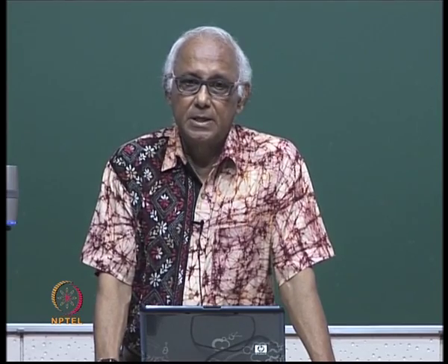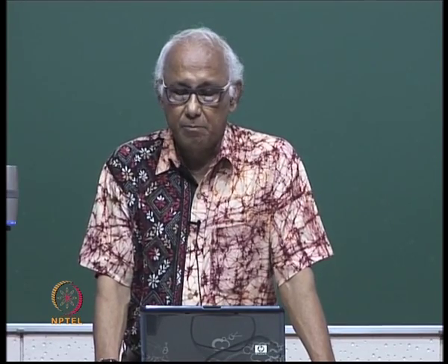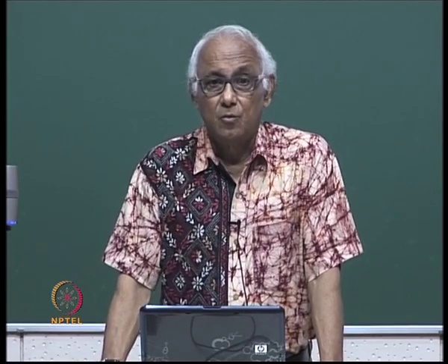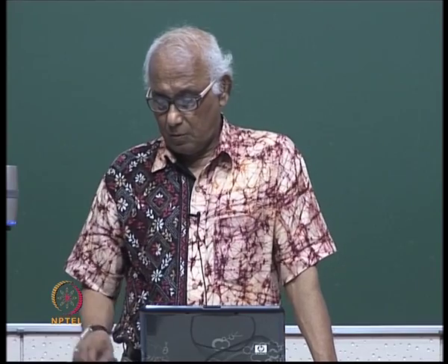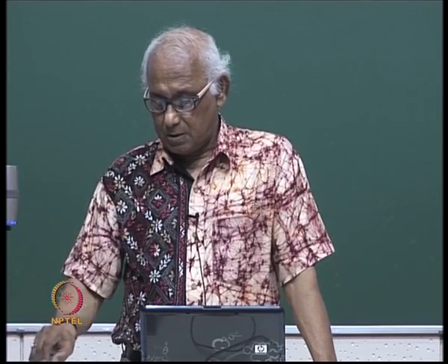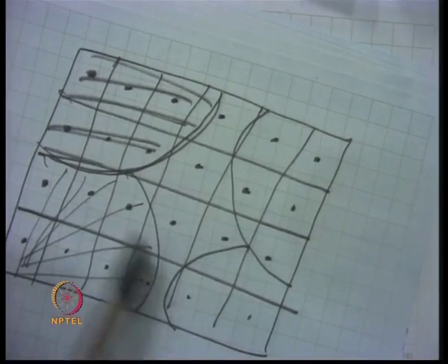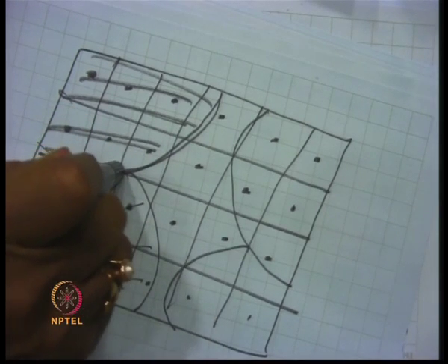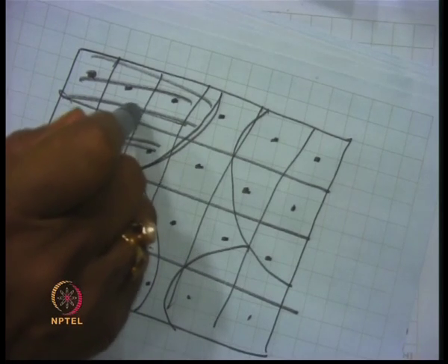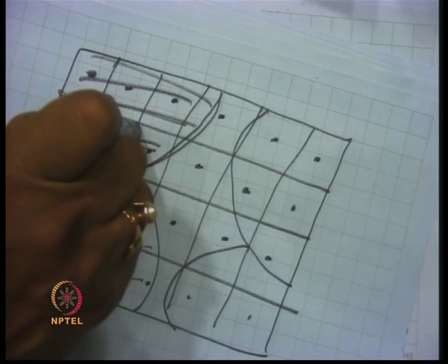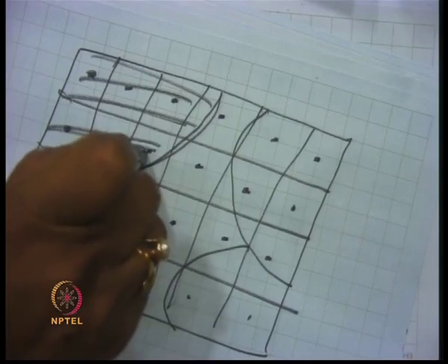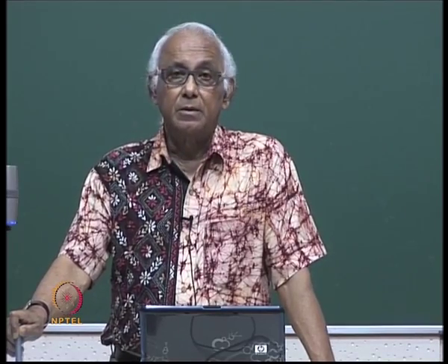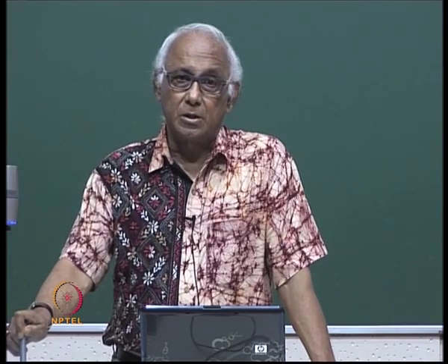These two parameters are very important, because for design purposes one should know, in each sub region, what the peak ground acceleration is for which the structure should be designed, and what is the likely amplification factor for that region because of the soil condition.